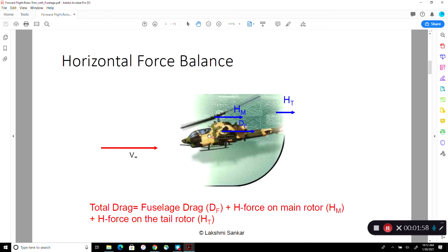So let's take a helicopter in forward flight. It's flying at a V infinity. The tip path plane is from the tip here to the tip here, viewing the helicopter from the pilot's left. So this is the inclination of the tip path plane. The angle between the red line and the tip path plane is called alpha tip path plane. Now we know the rotor produces an H force in the X direction behind the pilot. We had an analytical expression for the H force derived earlier on.